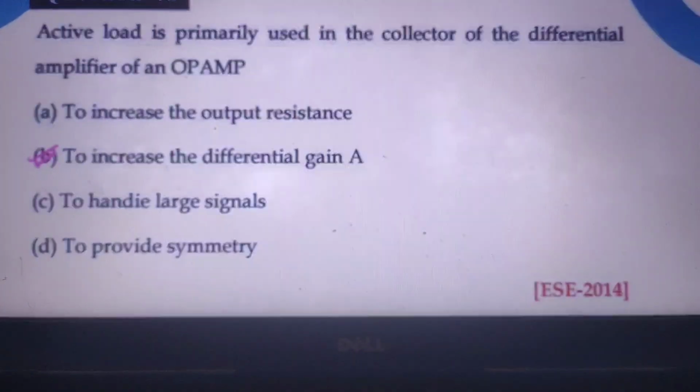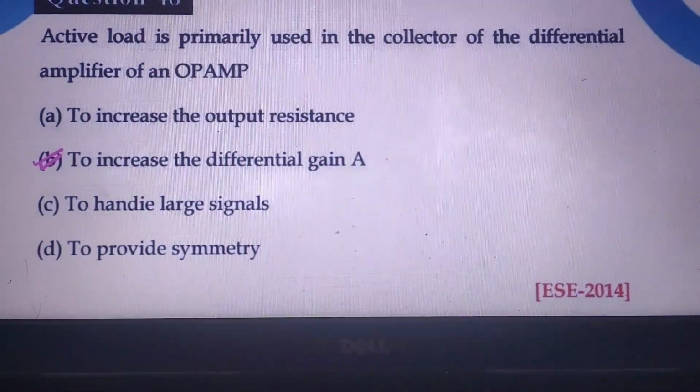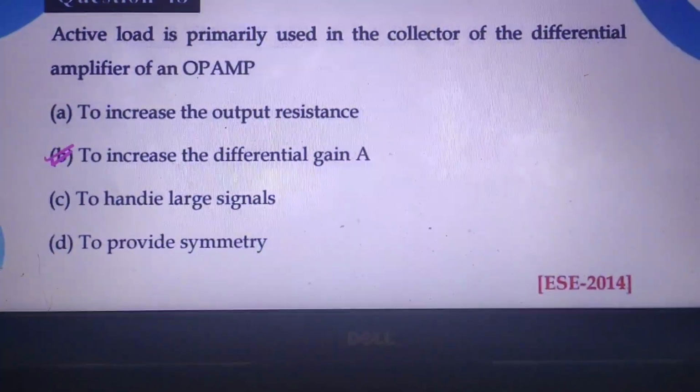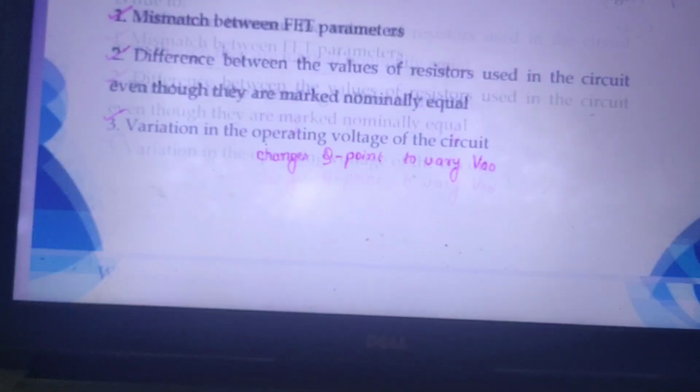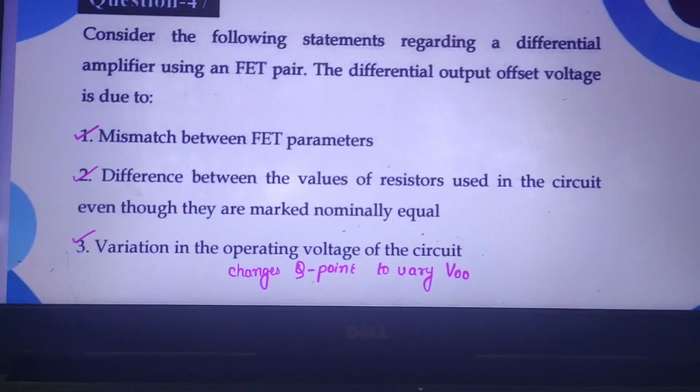Active load is primarily used in the collector of a differential amplifier of an op-amp, which is used to increase the overall differential gain.